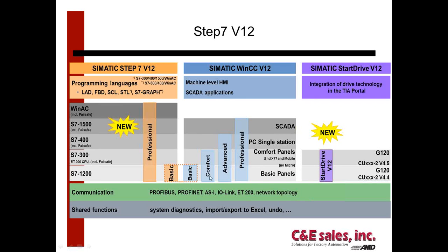If we move up to a higher level of panel, it's the Comfort panel, and that's actually in a widescreen format, which capitalizes on screen technology today, which gives you more power and less money to purchase the screen. Advanced is where we get into a PC-based HMI, and then Professional is our actual SCADA application.